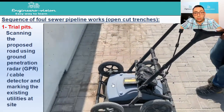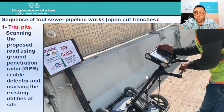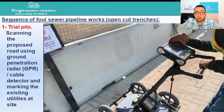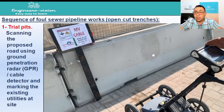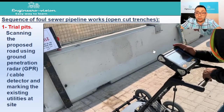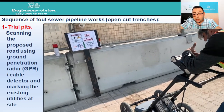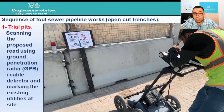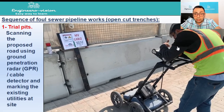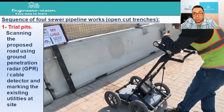This is something called ground penetration radar. This ground penetration radar will help you to know the exact location of the existing utilities, and it will give you the depth of these utilities, at which depth you can find this utility. As we can see here, the technician is reading the screen to determine the exact location and to let the site people know where is the location of this cable.